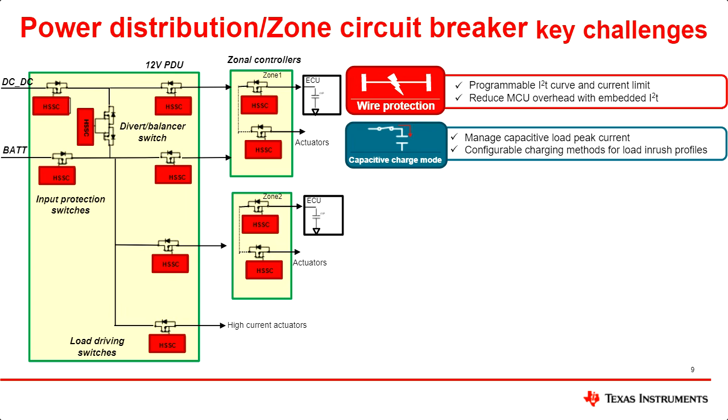Another point here is that most of the motor loads have a very big capacitance at the ECU output. So devices need to have some capacitive charging modes integrated, which will help the controller to drive these loads.